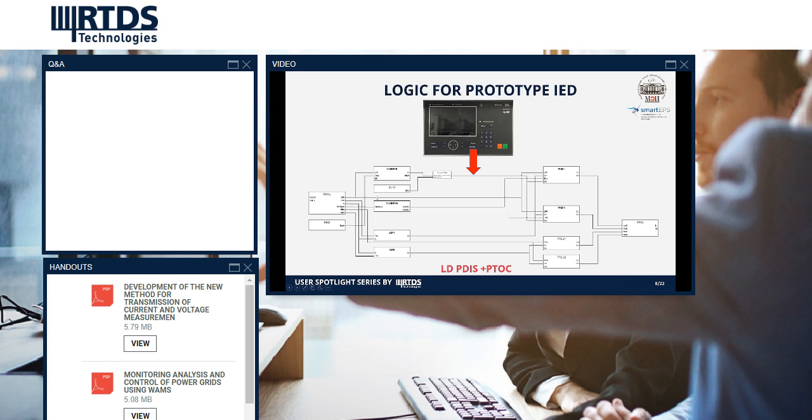Logical nodes PSB provide information of resolution or blocking signals to account for the mode of swinging. Logical node ZDIR is designed to perform the function of a power direction relay. Logical node PDIS is designed to perform the distance protection function, two-stage.